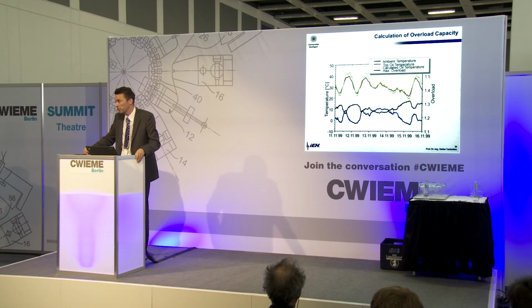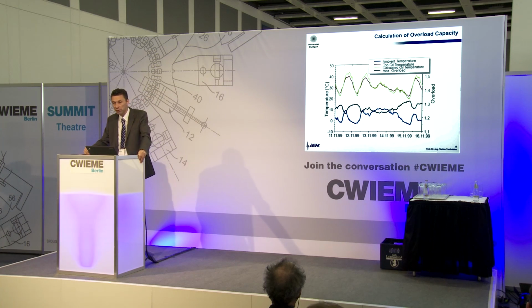This is especially maybe a solution for the wind farm transformers, because these transformers are fully loaded, especially at times when you have strong wind. Strong wind in turn means good cooling of the transformer, so at these times you can really also overload the transformer, and by means of such a monitoring system you can calculate this.